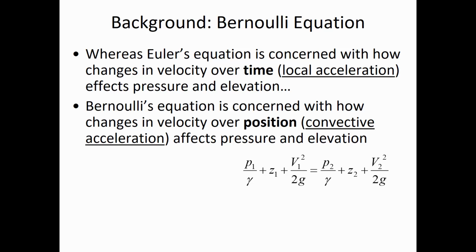And so overall, the units of this is going to be meters, because the newtons cancel out and the meters squared cancel out. All we're left with is meters in the denominator of a denominator, so that goes up to the numerator. So we've got units of meters for the pressure head, which is lucky because we want to add it with z, which is some distance, an elevation. It will also have units of meters.